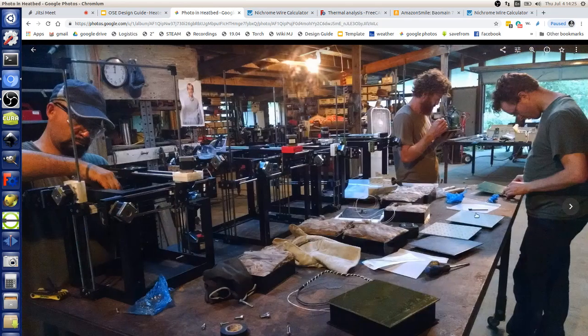More details of how we were doing. Here we were cutting. There you see these surfaces here are the double-sided 3M tape. So we put that on the steel surface first. We peel one side, roll it on. The way to apply it, you don't peel the entire side, you peel a little bit, and you kind of roll it on while peeling off the tape of one side, so you don't get bubbles in there or get it on straight. Because once you get it on, you pretty much can't take it off.